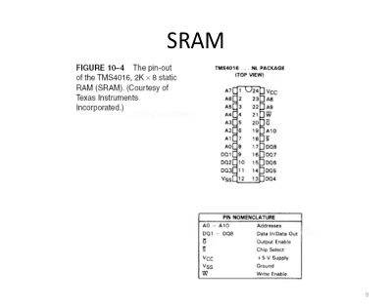Let's count. So we should see 11-bit address. So we count from A0 through A7, and there's some other pins spread out here, A8, A9, and A10. So total, you have to have 11 pins.